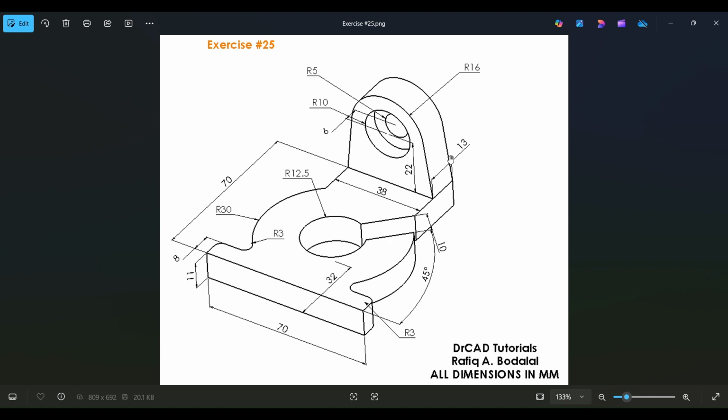Step two is to work on this lug feature. For that, we're going to sketch the base profile of this lug, and then use the extrude boss base feature to create the thickness. And again, here we see that thickness is 13 millimeters. And for the base profile here, where we use the extrude boss base after sketching the profile, we extrude this to a thickness of 11 millimeters.